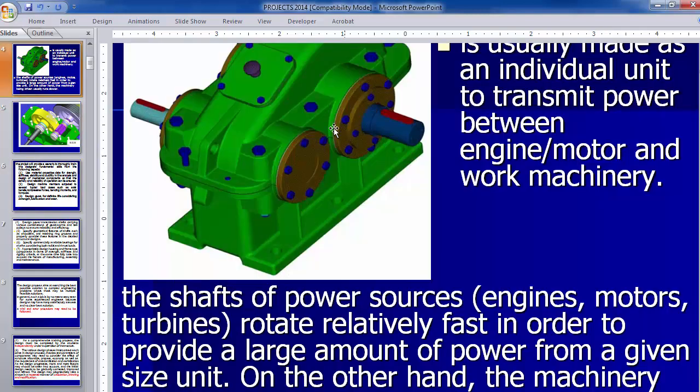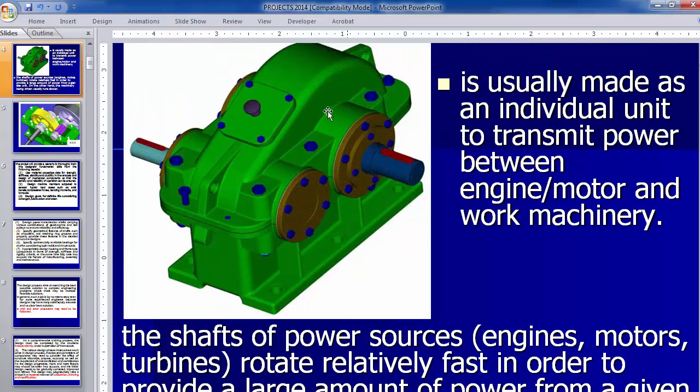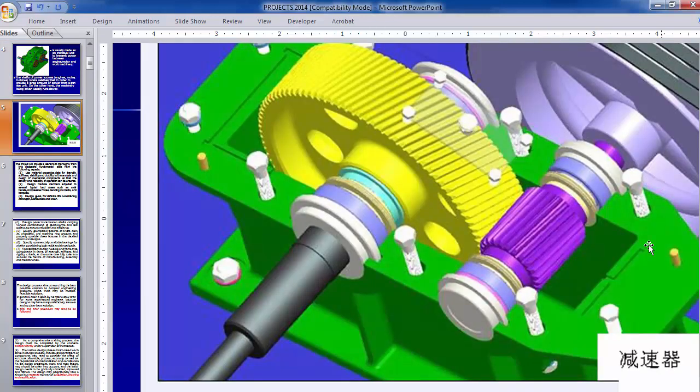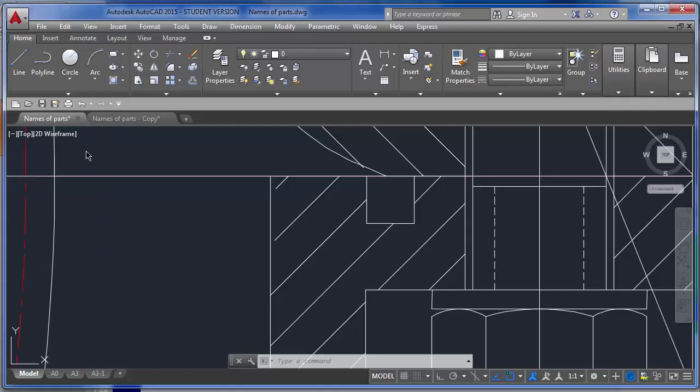Actually, when these two gears rotate, this gear will take the oil from the bottom and it will hit this upper portion and it will go somewhere else here. So we can collect this oil from the upper portion by this groove, and take it all the way to the bearing, all the way to here. Because in this case, it didn't go to the bearing, it just drains out here. But we can make it go to the bearing, like in our case.